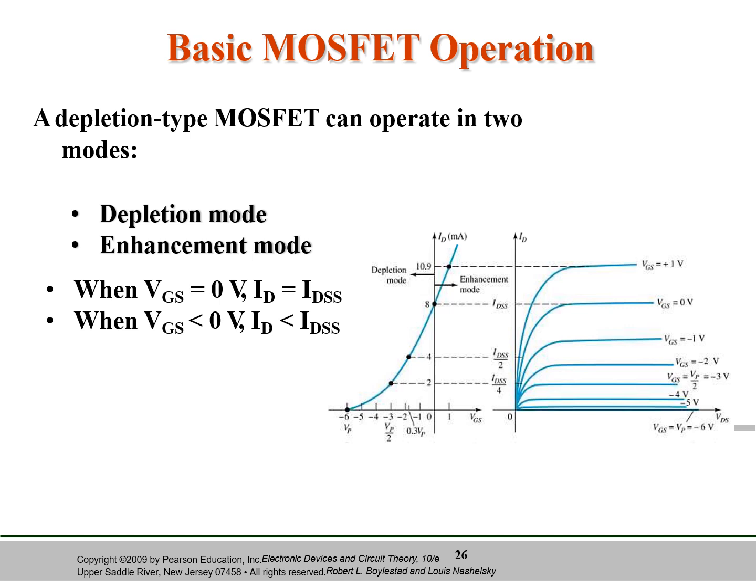So when you give VGS equal to 0, some current flows through the MOSFET. But when you make VGS negative, what happens? ID reduces. So what happens if you apply a positive value of VGS? The reverse operation happens and ID increases. I'll repeat. When you give VGS negative, there is a recombination of holes and electrons, which causes the reduction in the number of free electrons in the n channel. So ID decreases. Positive value of VGS, the reverse operation and ID increases.